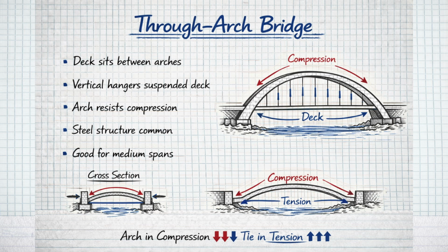8. Through arch bridge. In a through arch bridge, the deck passes through the arch, which rises above the roadway. Vertical hangers connect the arch to the deck, supporting it from above. The arch carries compression forces. This design is common in steel bridges.